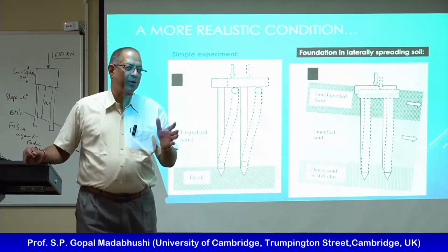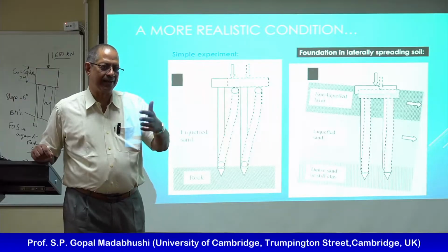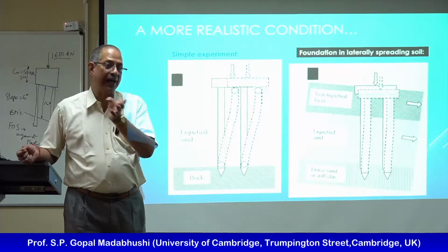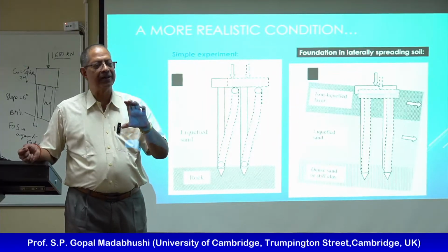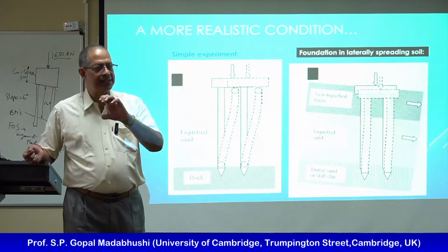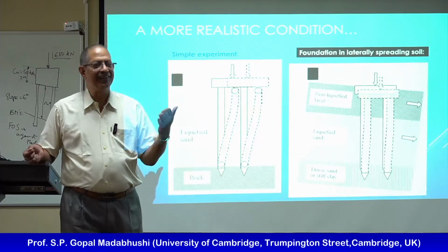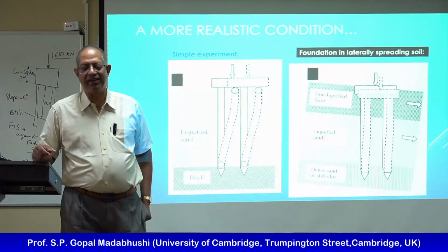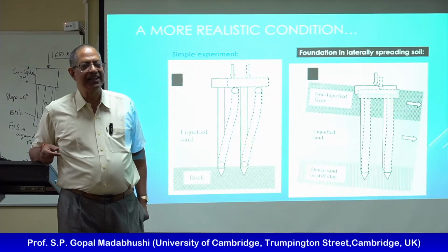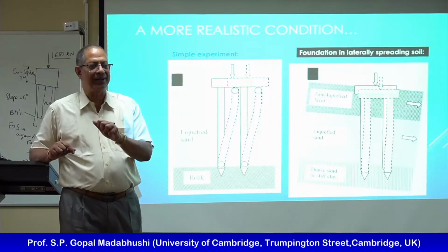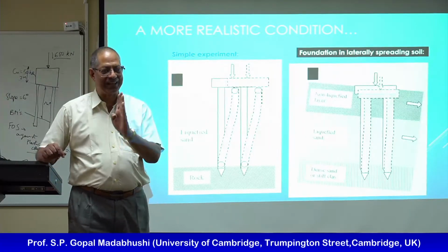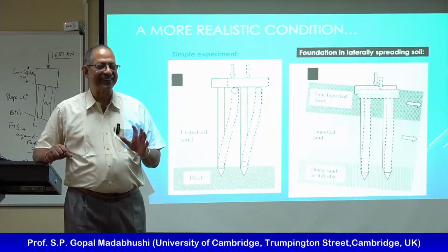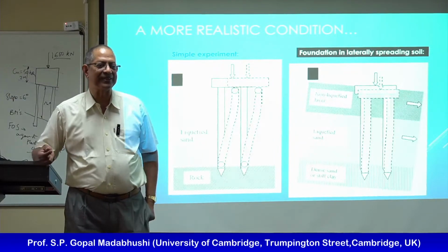Yeah, okay, you're talking about post reconsolidation after the liquefaction. The belief is yes. In fact, if anything, you'll get better because if it is sand, it would have densified, so you'll get better resistance than before. During liquefaction, one of the current projects we are doing is we got a monopile, we liquefy the soil and pull the monopile through the liquefied soil before the pore pressures are dissipated. The results are yet to come, but that's something we are trying.